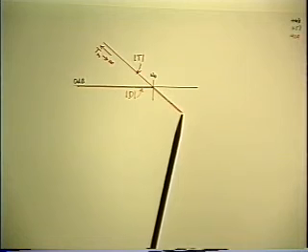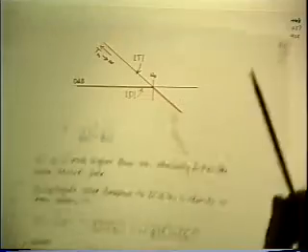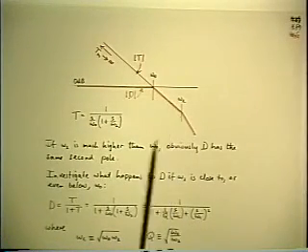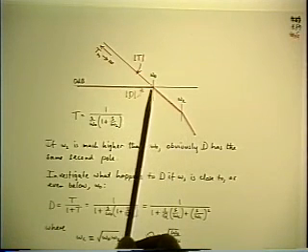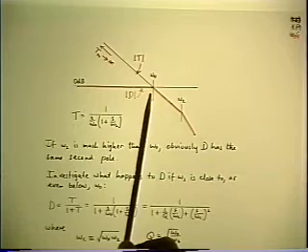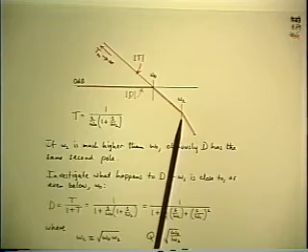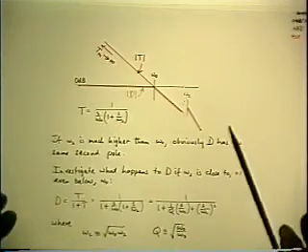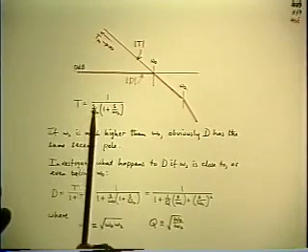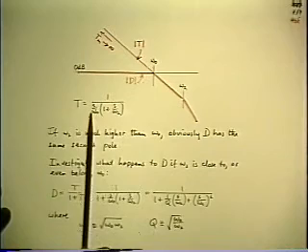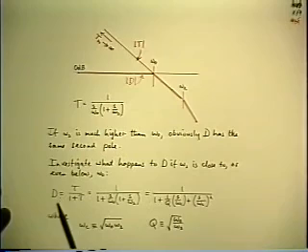Now we're in a simpler position to start making the problem more complicated in a useful manner, which is to consider what happens if you have a second pole in T. Now, if the second pole is a long way above the original crossover, then D is equal to T whenever T is small, so D will have the same pole that T does. And here's the formula for T. The original single slope crossing unity magnitude at omega 0, and then you have a second pole at omega 2.